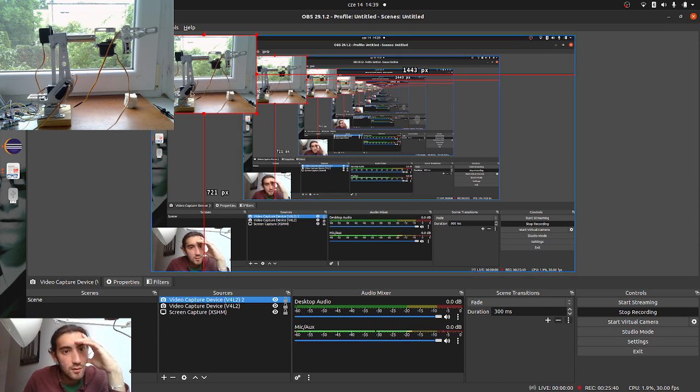But first, I need to define the transformation matrices between these frames, and then I will compute the forward kinematics with given angles for all of these frames. For example, if the base frame is rotated clockwise or counterclockwise, I need to put all of these angles, probably in radians, into this equation for all of these frames, and then achieve a transformation matrix of the end effector, this point in space related to the base frame.